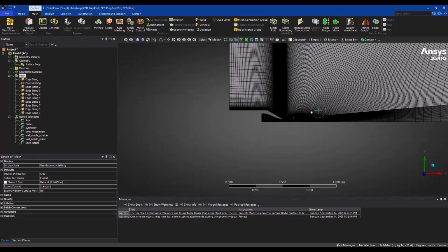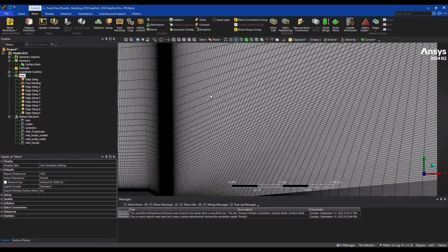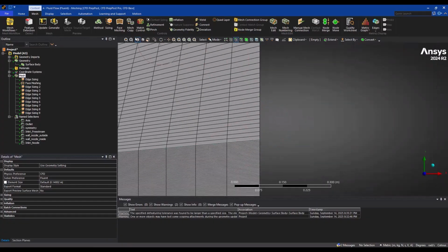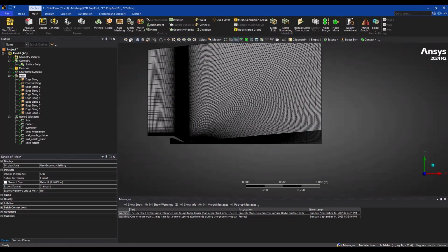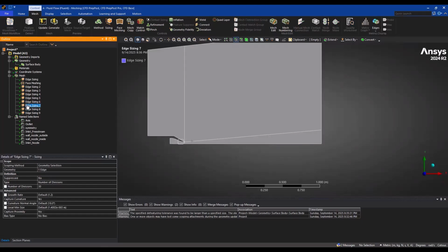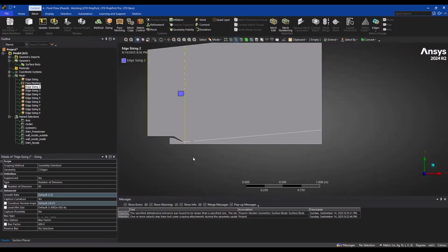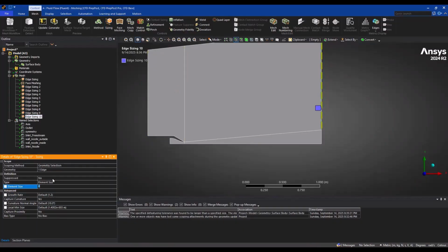Okay, any questions about the meshing? We should define how many cells there are on this edge. This is 80 cells. So let's make it 120. I will define the cells separately here. They will be 120, but the spacing will be decided by ourselves. So let's make it 120 and put some biasing here.